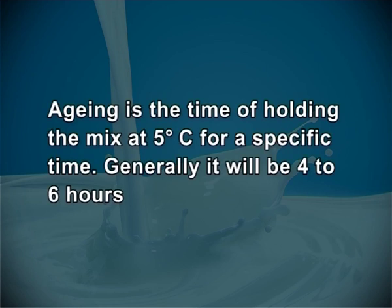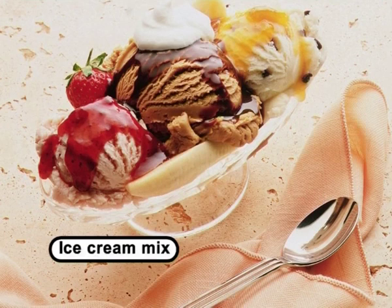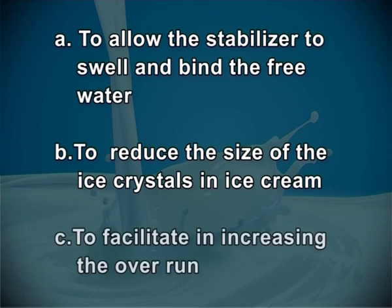Aging. Aging is the time of holding the mix at 5 degrees centigrade for a specific time. Generally, it will be 4 to 6 hours. The aging period depends on the kind of stabilizer used in the ice cream mix. Sometimes ice cream mix will be kept overnight for aging. The main objectives of aging are: A. To allow the stabilizer to swell and bind the free water. B. To reduce the size of the ice crystals in ice cream. And C. To facilitate in increasing the overrun.